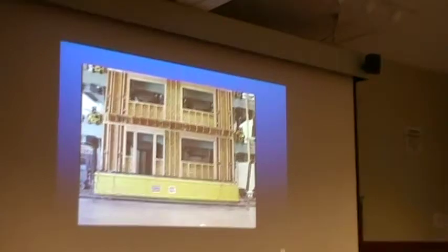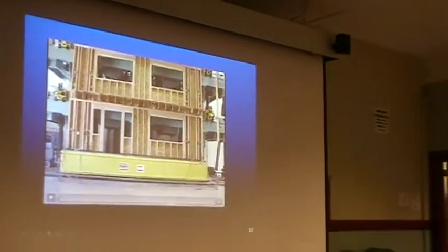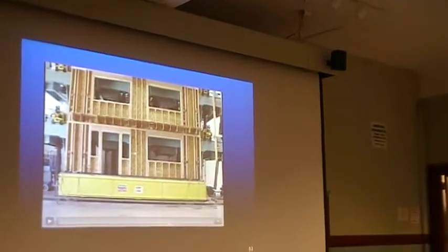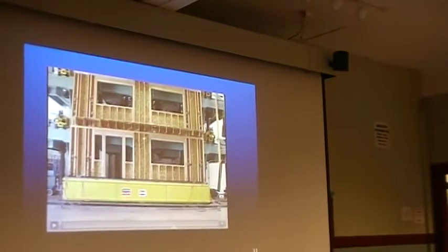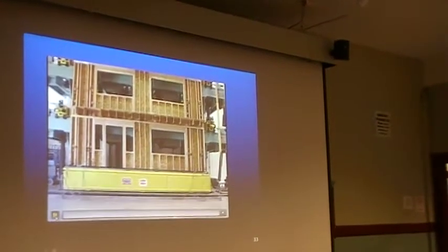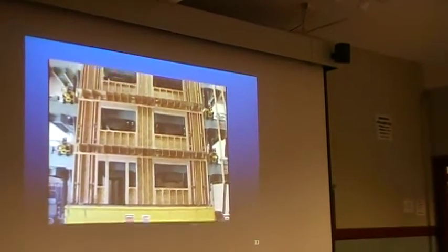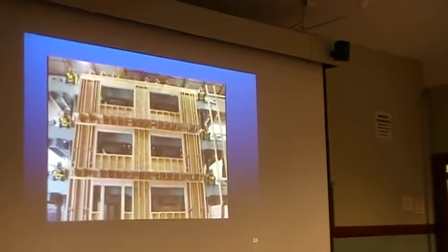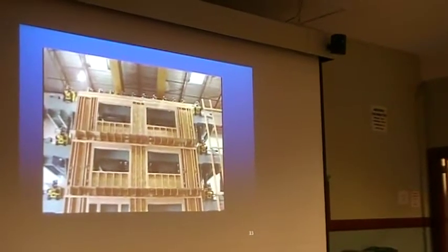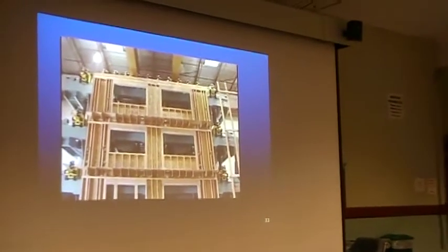Here's an example of a 3-story shear wall. If you notice, you've got something to carry tension over here. You don't have anything over here. There's no straps in here. It's an example of what happens when you don't keep pushes and pulls in mind. There's only 3 types of forces. It doesn't matter if the wind's pushing on this thing or you're shaking the base and having it accelerate. You both put forces into it. So this is a shake test.